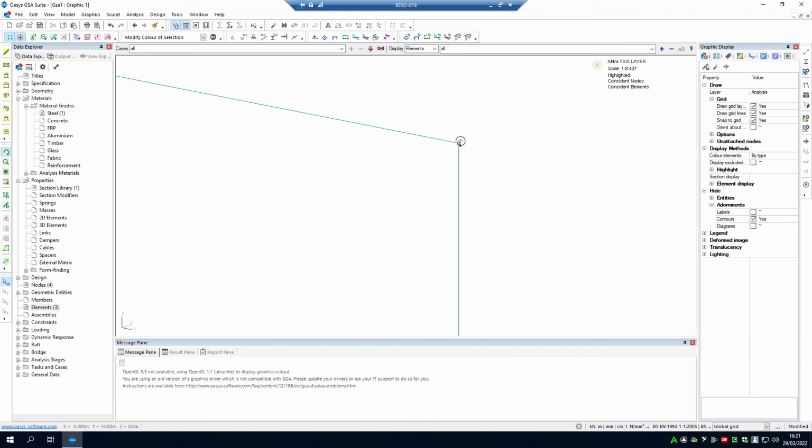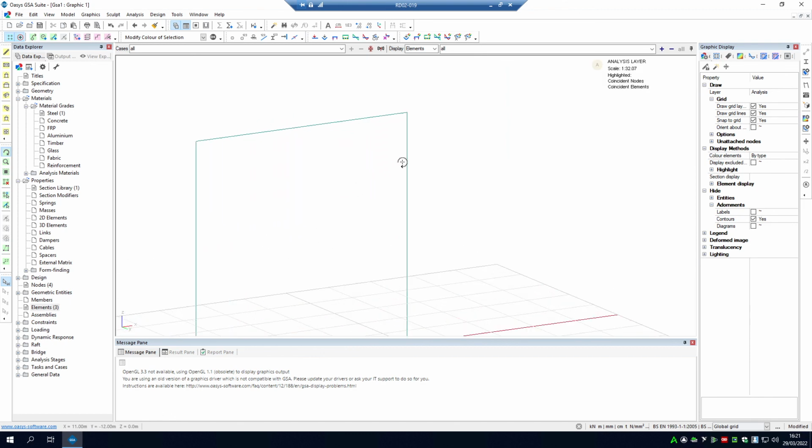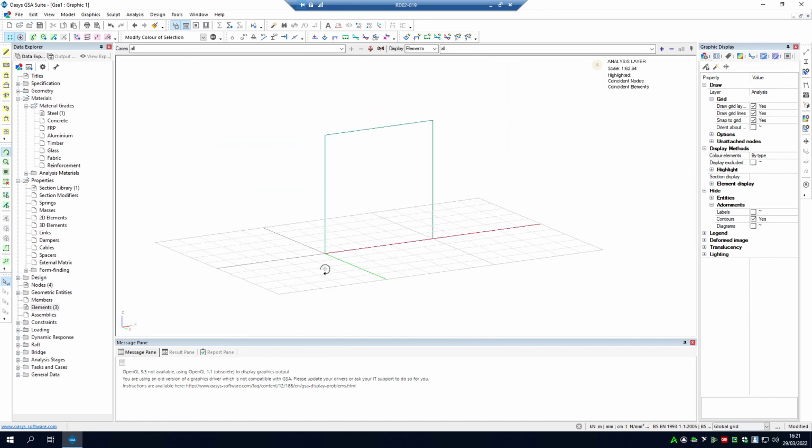Unless you specify otherwise, every node that has 2 beams or more coming to it, you can consider them all to be welded together. All axial bending stresses, they all transfer directly through it as if it was just one big element. If you want to create hinges or pin joints or anything like that, you're going to have to specify that. Otherwise, every single combination is automatically considered fixed together. All right, so that is how to create your elements and how to put them in your model.